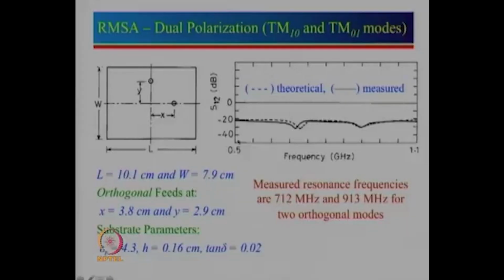So, what we are trying to show here is that if we have a feed point over here which is x, for this feed point, just for a moment think that y is not there, okay? This feed point is not there. So, if this is only x, then what will happen? It will excite a fundamental mode which is 1.0. So, 1.0 means this will be plus V going to 0 and this will be minus V which is the maximum. So, since this is 0, this entire thing is 0.